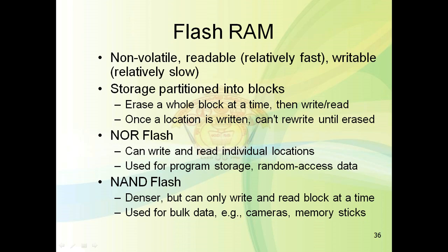NOR flash can write and read individual locations, but NAND flash we can only write and read block by block, a block at a time. NAND flash requires less area as compared to NOR flash, and hence NAND flash is denser as compared to NOR flash.